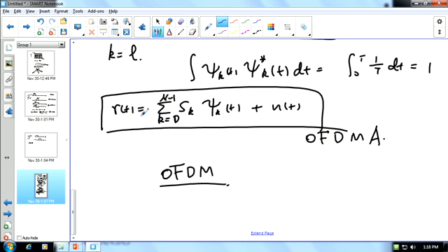And this is written in continuous time domain, right? We have a time t. And in reality, what we do is we have discrete time symbols. If you take the discrete time samples, discretize this t, this simply becomes a fast Fourier transform. Okay? And we can actually prove that, but that's irrelevant to this class. And some of you have already taken my wireless communication class where we introduced that there. That's essentially a discrete time Fourier transform there. All right, so any question about OFDMA?